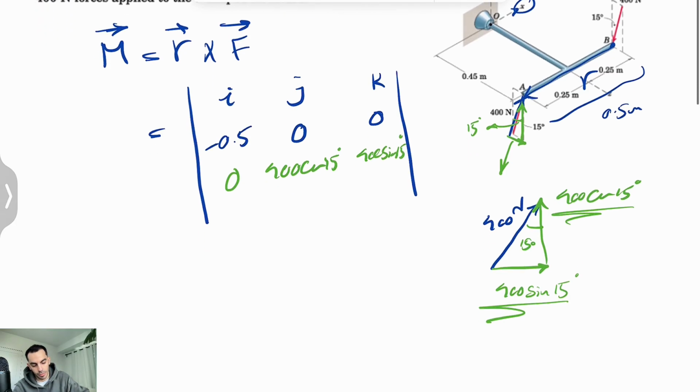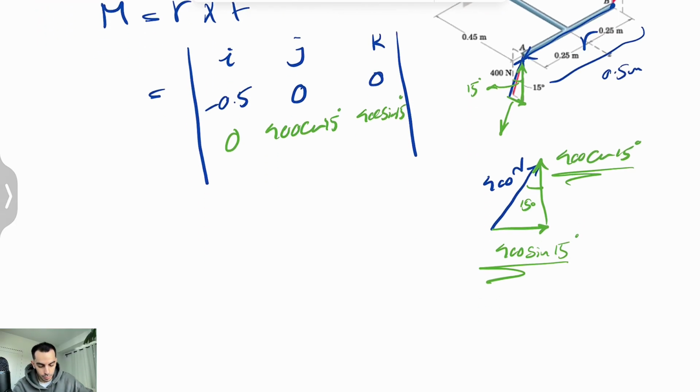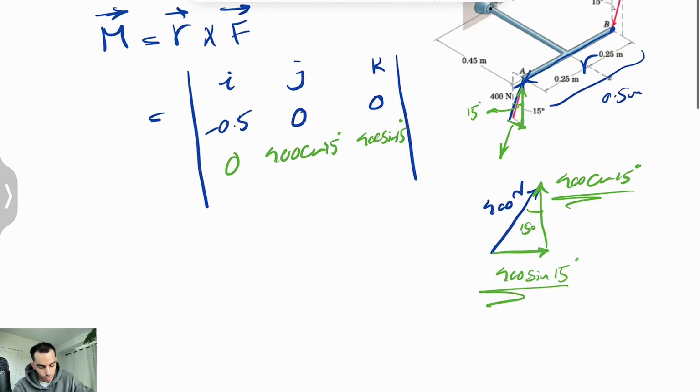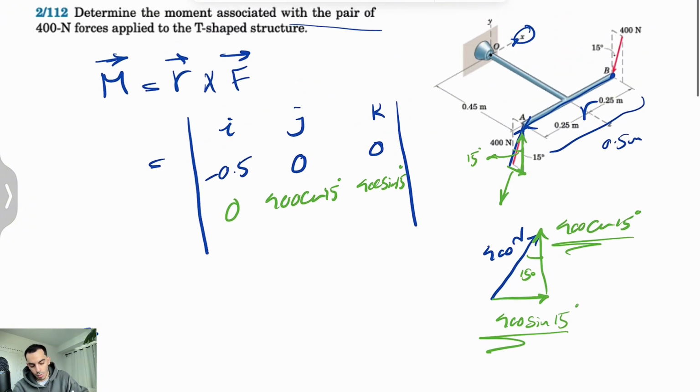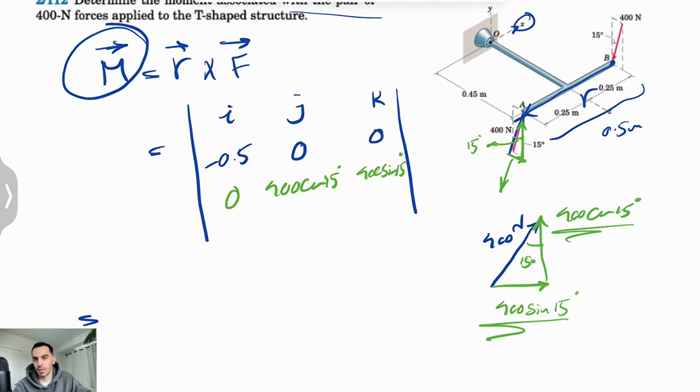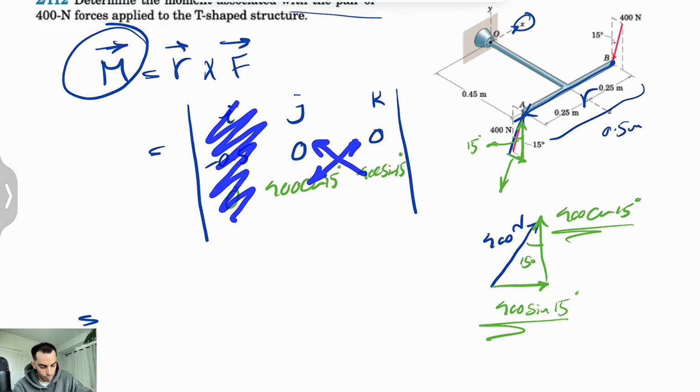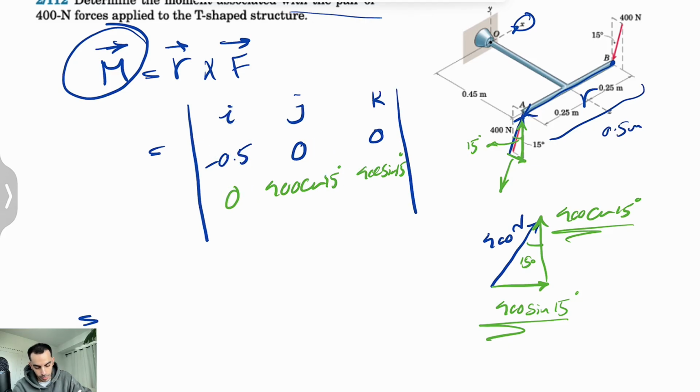And the rest of this is finding the cross product. The moment, first of all, is going to be a vector that has i, j, k components. Let's find the x component with the i unit vector. For doing the cross product, we're just going to cover this and multiply these two, which is going to be 0, so nothing for that i.